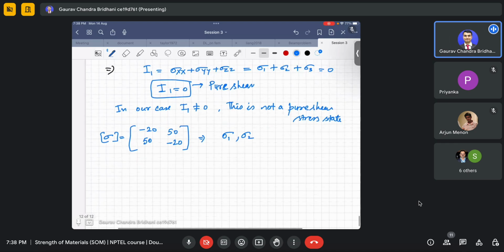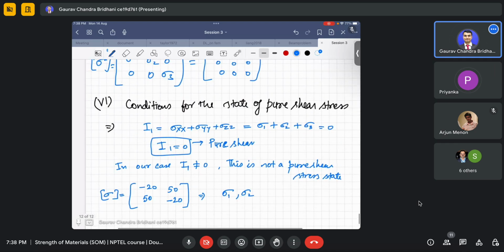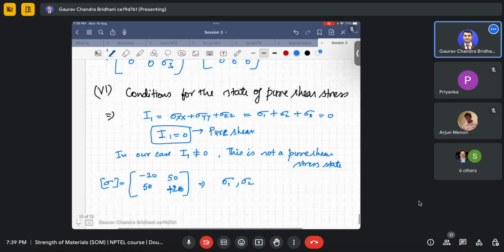Oh, sorry. Yeah, correct, thanks. It should give a 0, no? So it should obviously be plus here. Okay, so this is one check, and for the check for uniaxial stress I told you how to check it using I2 and I3. Just check whether I2 and I3 are 0 and I1 should not be 0. So that is for uniaxial.